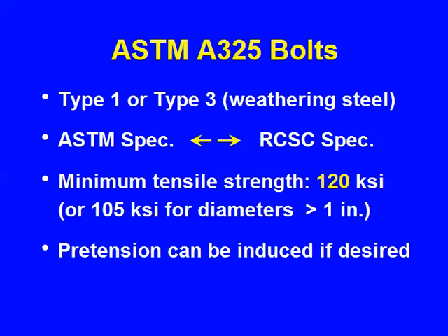Turning to the high-strength bolts, there are two types, 1 and 3. As you might expect, there was a type 2, but that no longer exists. Type 3 is weathering steel. We don't have to know what type. As a designer, you just pick A325 bolts and you're finished.